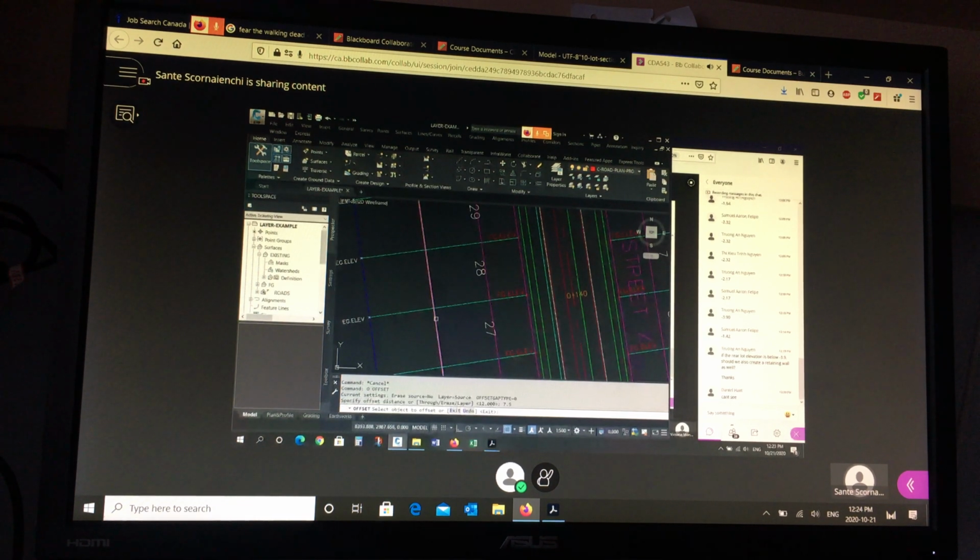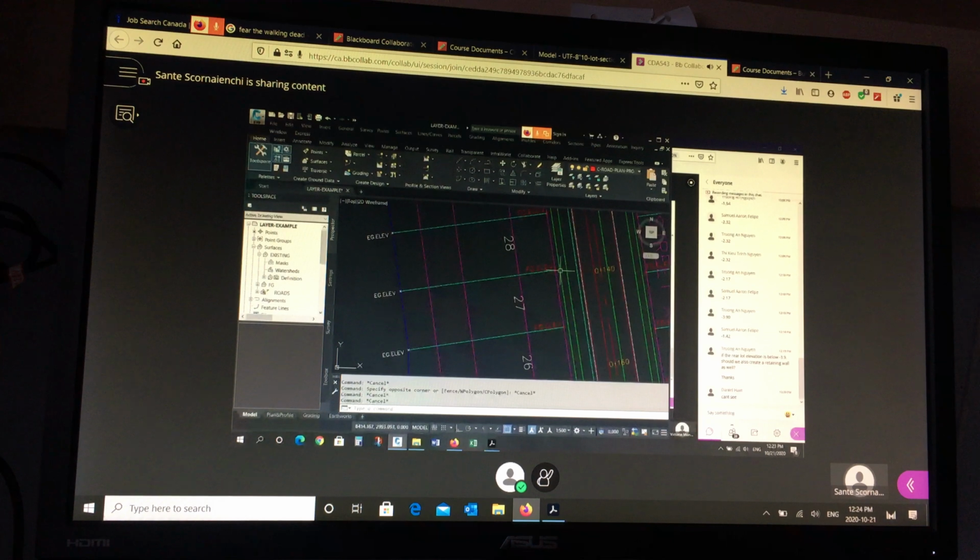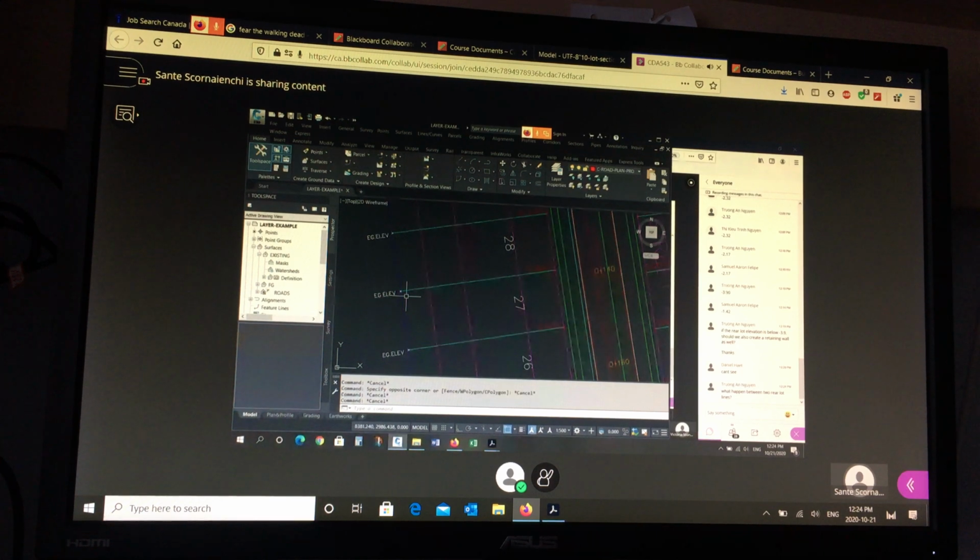And if you need it, this will all be 3-to-1 sloping. Right? So you're going to need, come up at 2%, take that number, bring it to the back, push it down 2.1 meters, go down 3%, go down 3-to-1, and then whatever you propose at the back, it's going to be still higher than the existing. The difference would be the height of the wall. So I'm just trying to give you an idea of what happens between 2 rear lot lines.